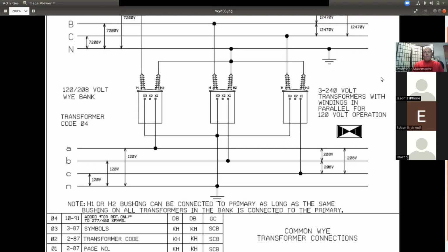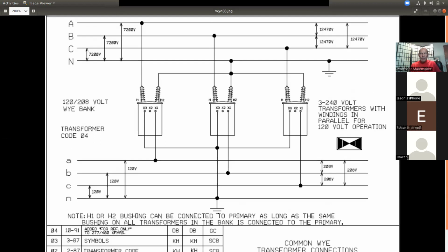Okay. Y has a purpose also. It's balanced. More of a balanced three-phase and single-phase. I need a good bit of three-phase and I need a good bit of single-phase, both at the same location. Good example of that is the college. There's a good bit of motor loads in those buildings, and there's a good bit of lighting loads, 120, 240 applications in there. So it's kind of like a 50-50 type thing. So in those cases, I'm going to use Y.